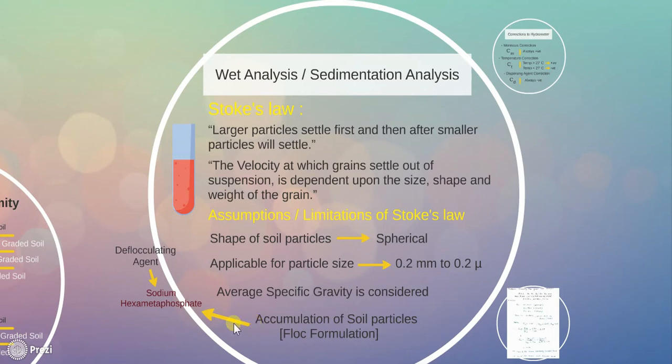Thus, some deflocculating agent like sodium hexametaphosphate or sometimes sodium oxalate must be used. So these are the assumptions or limitations of Stokes' law.